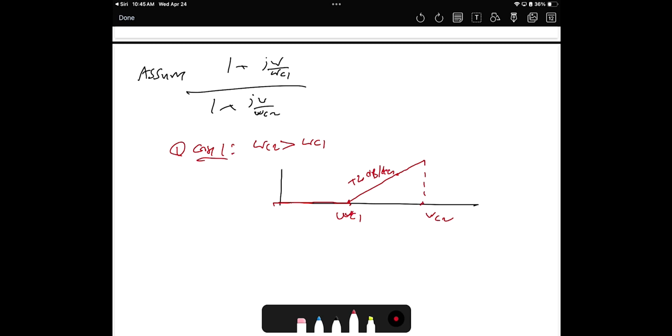So the slope will be 0, and it will be constant, because plus 20 and minus 20 cancel each other. So you can say that the pole and the zero can cancel their effects after a certain frequency, depending on where the critical frequency is.